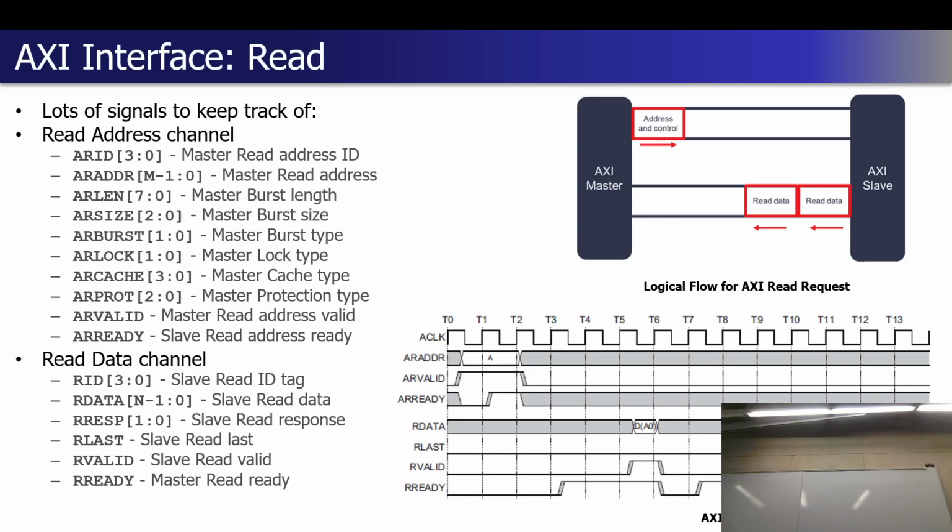There's reasons we sometimes have to do this, right? It's not actually shown here, but our data can be of different sizes, bit width. So it could be 8, 32, 64 bits. That's on the sender side. The receiver may not be capable of handling that much data at a time, and so we may have a need where the sender side is capable of handling 64 bits of data, but maybe the receiver is only going to be able to send 8 bits of data at a time. You would set AR size accordingly. That's a valid question. It's a good question.